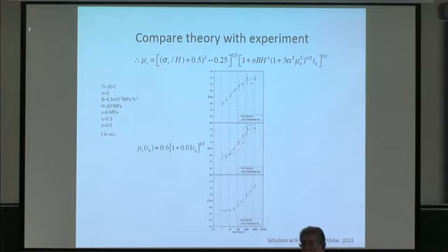If you apply it to the highest speed, the model is going to underestimate the coefficient. If you apply it to the lower speed, it will overestimate the coefficient of friction. Possibly that's because of not using the correct n value, possibly because the b value must change. But the point here is that it's within a factor, perhaps 20-30%, of the actual measured values.